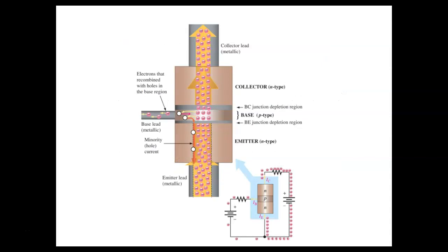So this is what we're showing. I don't identify this guy yet, so it's an NPN. Over here I've got 16 volts building up. Down here I've got 5 volts. So as soon as I do this, it breaks down the depletion region once we exceed the drop. For silicon, the emitter-base is going to drop around 0.7 volts. For germanium, it would be around 0.3. These are the two signatures.